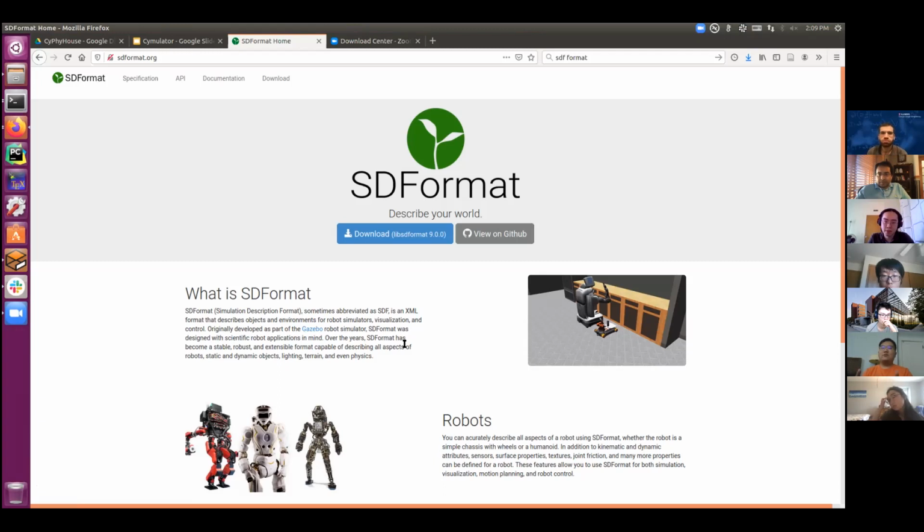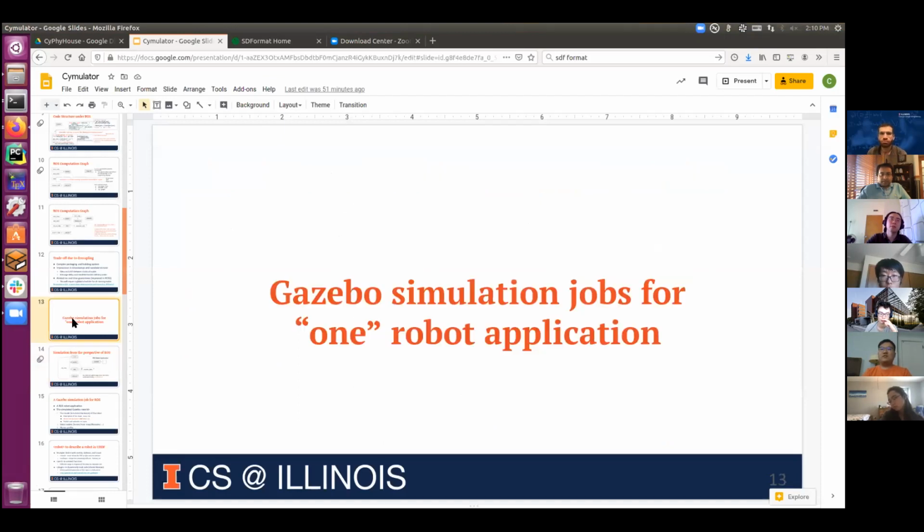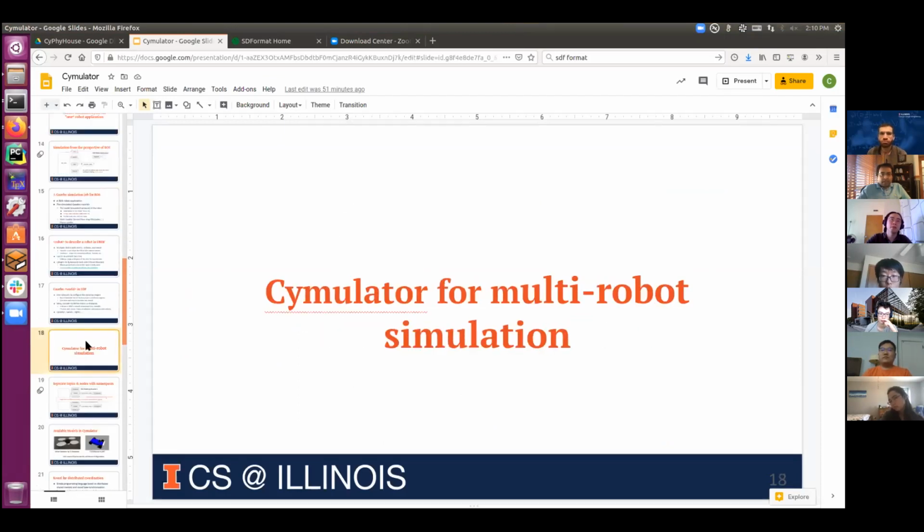But when I try to make some simple model in Blender, like making several squares to make up a house, then I can transfer it into SDF, and it can successfully load into Gazebo. So I think there are maybe some requirements for the transformation from Unity to Gazebo. Got it. Thanks.